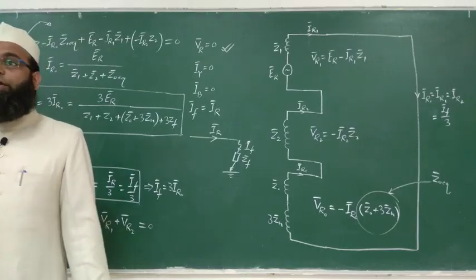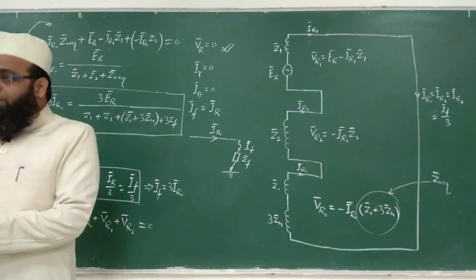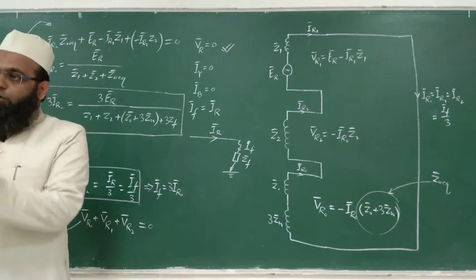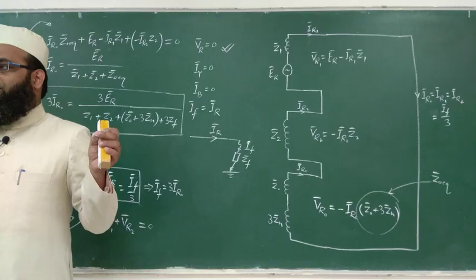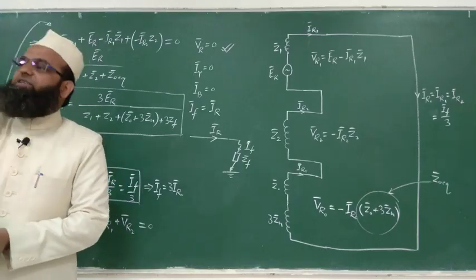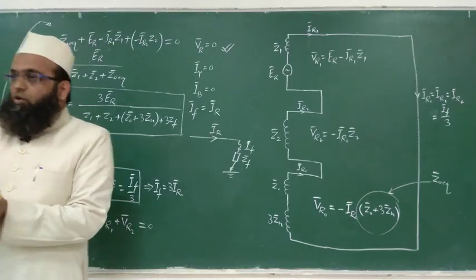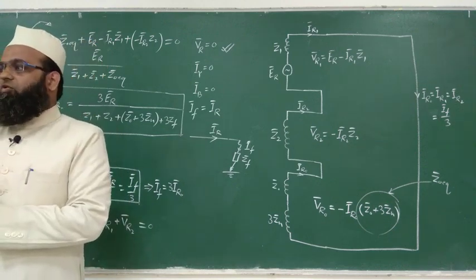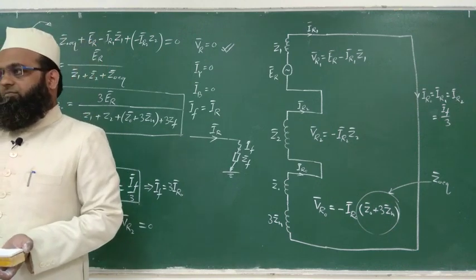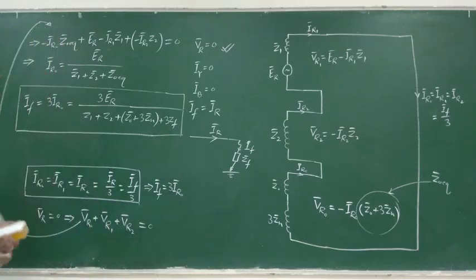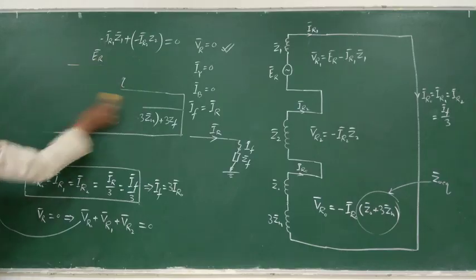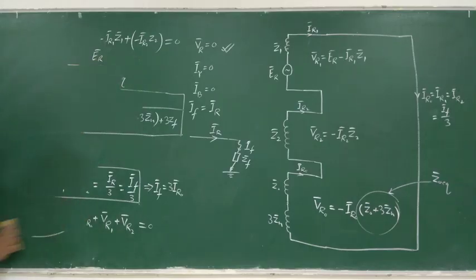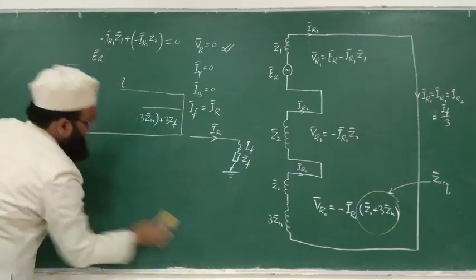For flow of any current, circuit must be completed. If your neutral is ungrounded, although R phase is touching ground, the neutral of the system is disconnected from the ground, so fault current will be 0. Clear?